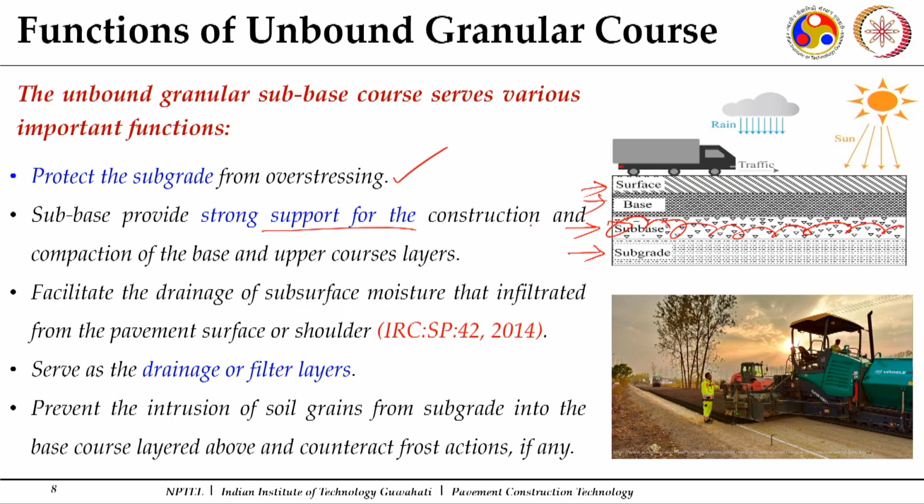Subbase provides a strong support, and as you move to the base courses you need mechanized construction. So, pavers may come up on your subbase course to lay your base courses, which may be cement treated or non-bound granular courses, in terms of a wet mix mechanism. So, it provides a strong support for the construction and compaction of the base courses and the upper courses of the pavement structure. The one major important function served by this layer is the drainage of surface water. This is an important aspect.